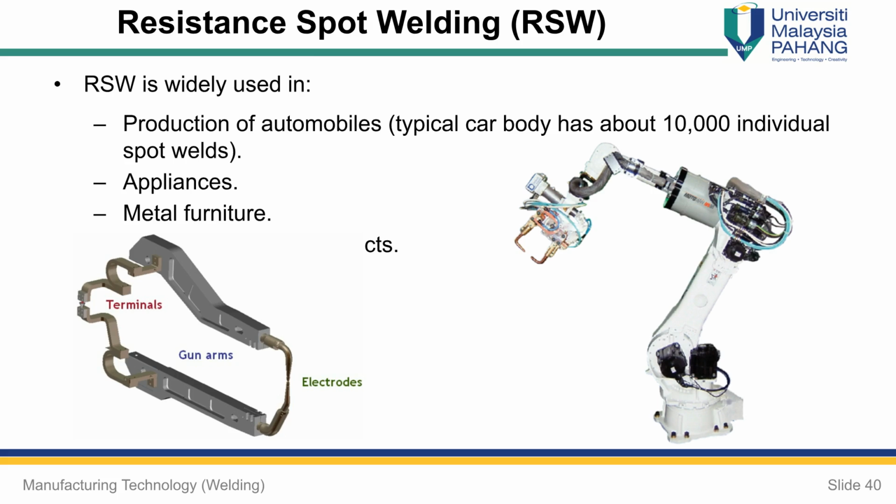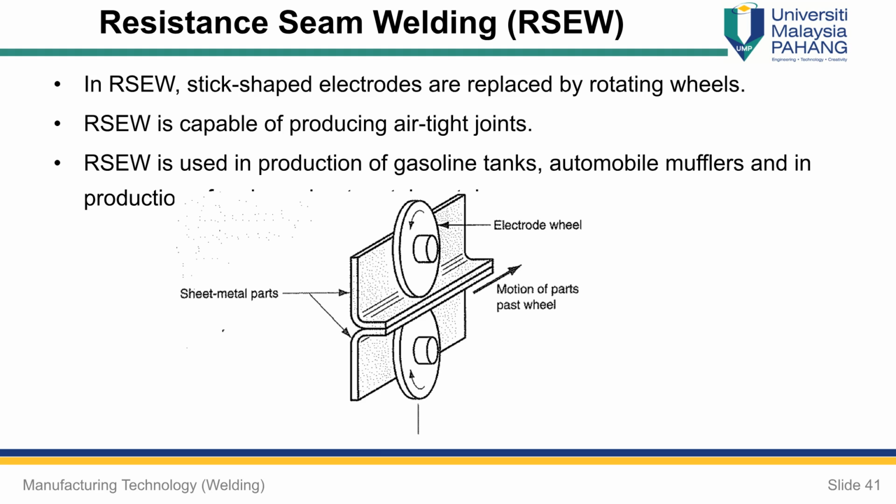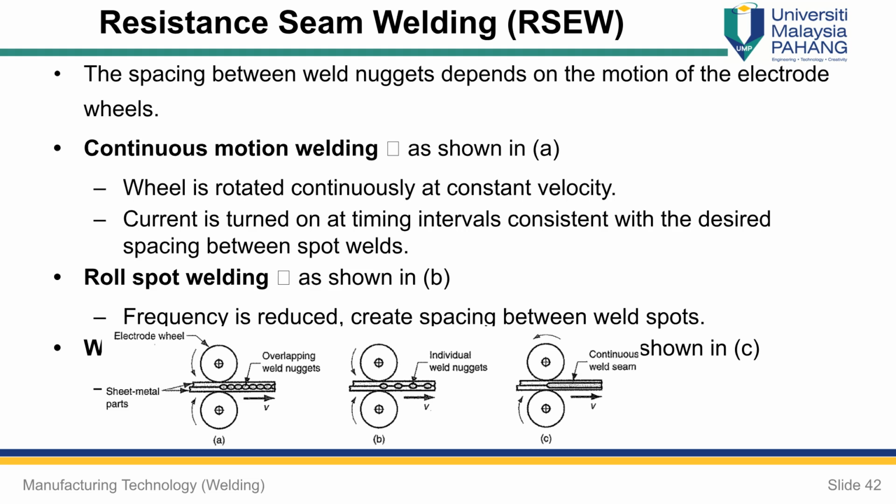It uses no shielding gases, flux, or filler metal. While current is very high, the voltage used is relatively low. Success in resistance welding depends on both pressure and heat. Pressure forces contact between the electrodes and the work part, pressing the faying surfaces together to achieve coalescence.